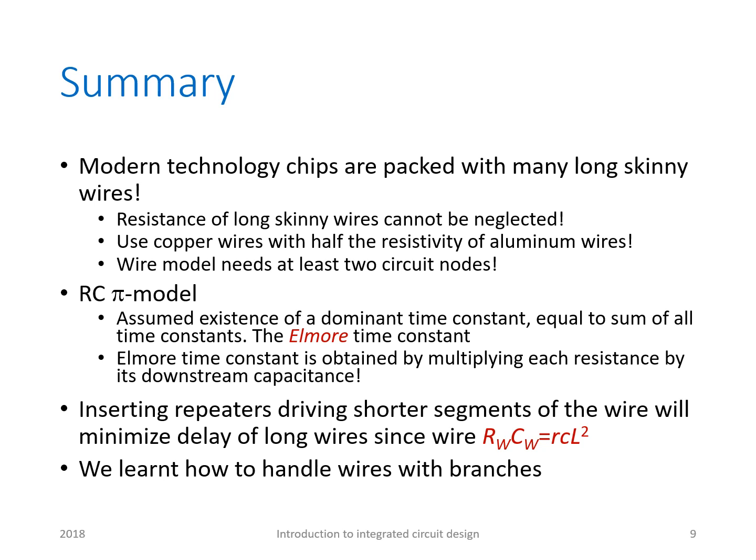Inserting repeaters to drive shorter segments of the wire will minimize the delay of long skinny wires. Otherwise, the delay increases with L squared. And we have learned how to handle wires with branches.